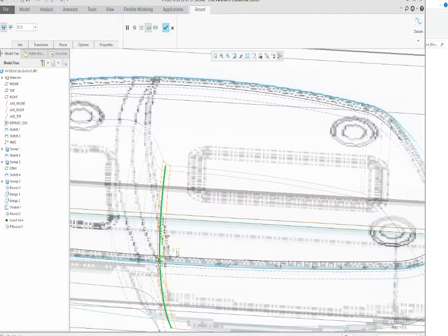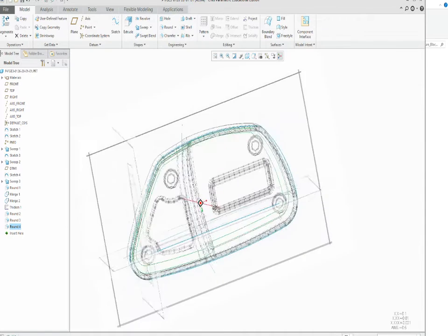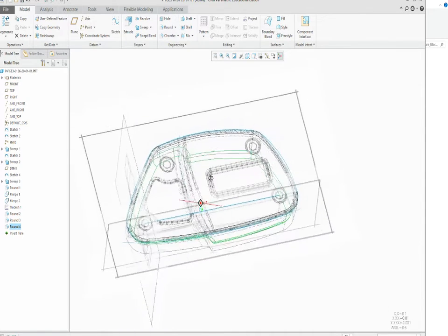So if I go 12 thousandths on a ball end mill on the inside, I might get it up a little bit farther, like 20. If I use 20, they can use a 3/16 on the design. I'll hit check. Now I'll try to ball end mill all the way around on the inside here, and I'll go with 20 so they can use a ball end mill all the way around on the inside.